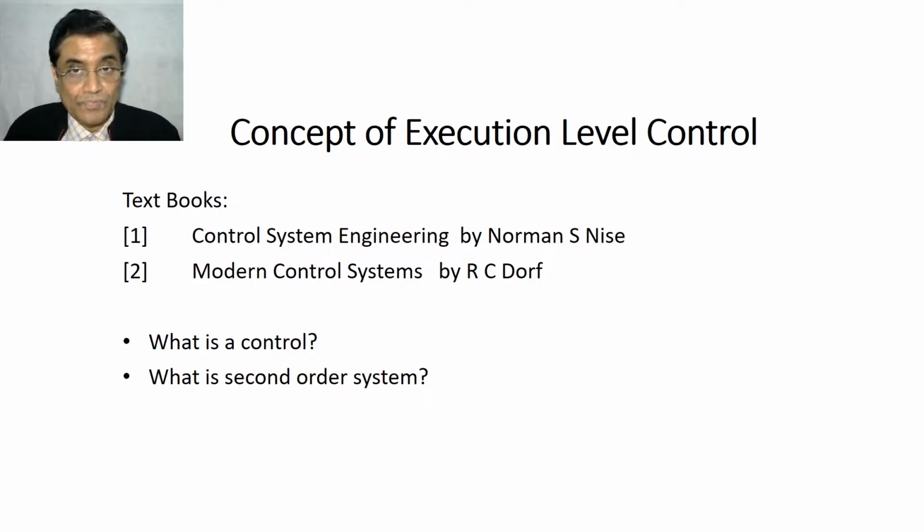So the computer is a controller also, right? That is a planning level controller. You are solving programming, running some algorithm, getting some result. Those are called planning level control. After getting those outputs in the planning level control, they will be fed as an input to another controller, which is known as the execution level controller, right? Which actually will execute the task, and that will make your robot move in a desired fashion, right?